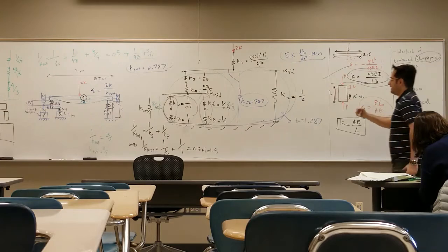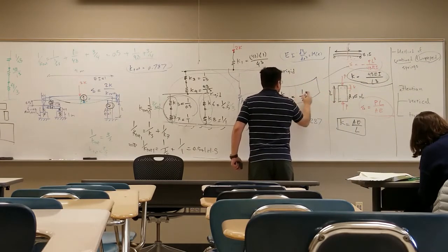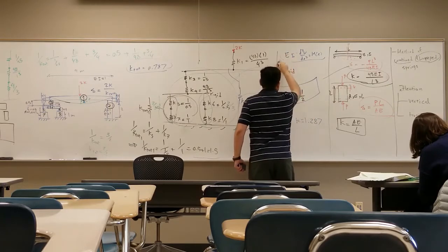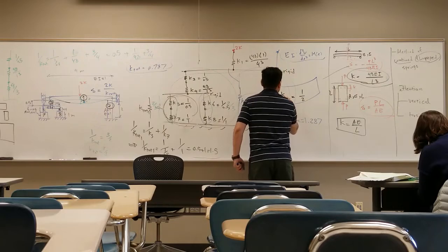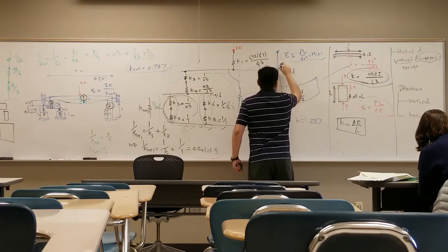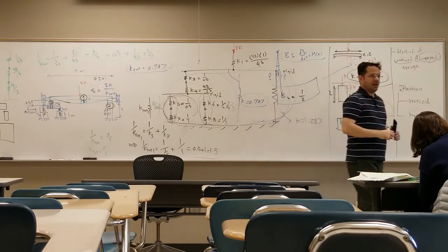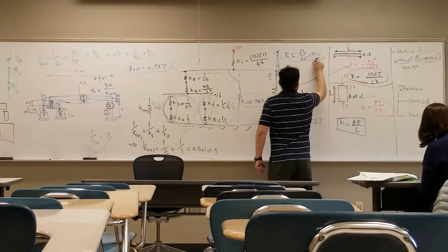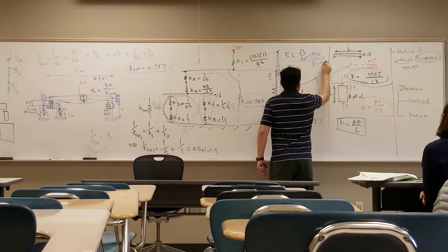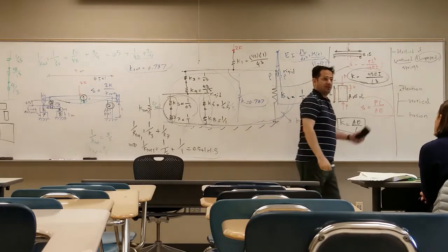Then you take an element of the beam, let's say with a radius of curvature, and with the deflection theta, and then you can use that equation. Then there were some other terms here, some square root of 1 plus dv/dx squared to the 3/2, a nonlinear term.